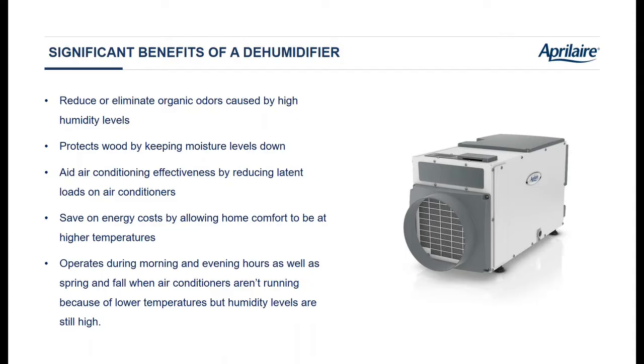A side effect of this, keeping the relative humidity under control, is that human comfort, what we experience as a comfortable indoor condition, is related not just to temperature, but also humidity. You'll be comfortable at a warmer temperature if we can keep the air drier. The impact to the consumer is, if they're using a whole home dehumidifier to keep the relative humidity lower, they can adjust the cooling set point on their thermostat. If they do that action step, then they will save a significant amount of money on their cooling bill.